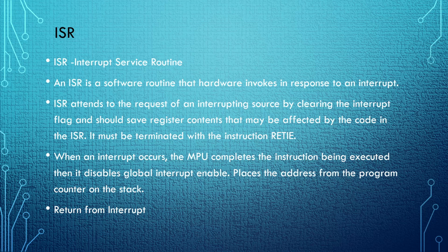An ISR is a software routine that hardware invokes in response to an interrupt. ISR attends to the request of an interrupting source by clearing the interrupt flag and should save register content, as they may be affected by the code in the ISR. It must be terminated with the instruction RETI.